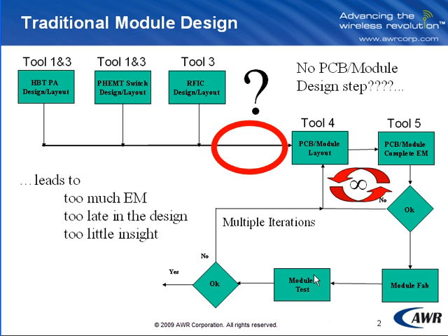Moreover, because there's actually no PCB module design step being done, in other words, the module is viewed more as a mechanical integration technology than an electrical design one, we often leave the actual electrical analysis or electrical design to an analysis step post layout. What this does is it really takes away the ability to do parametric design, optimization, tuning from the electrical engineer and forces him to go into more of an analysis mode, which leads to many iterations in time-consuming EM, which ultimately lead to multiple iterations of the design itself.